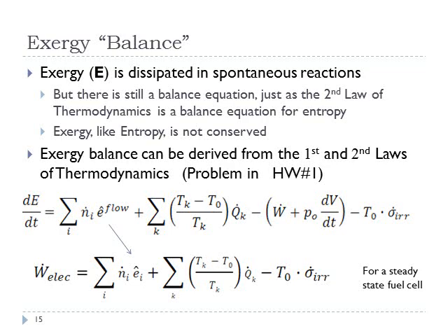And we're not going to be working that much with mechanical work or any kind of piston type of system. So W dot is normally just W dot electrical. That's the other approximation that's gone into this equation. So the way we got from the first equation to the second one was if we assume steady state.